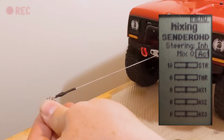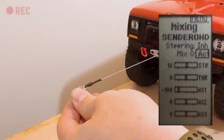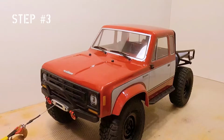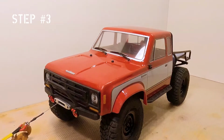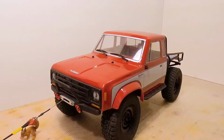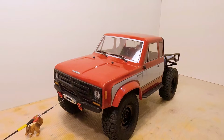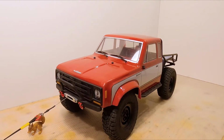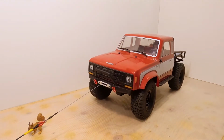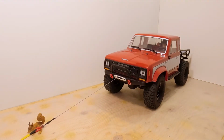It's like living in the future. With the mix disabled, your throttle and winch are controlled separately as usual. Since the winch control is not proportional, when the mix is enabled, the wheels will likewise turn at a fixed rate. Now is the time to fine-tune that rate. Keep in mind that you most likely want to keep the winch line under slight tension at all times, or risk a tangled mess of winch line.